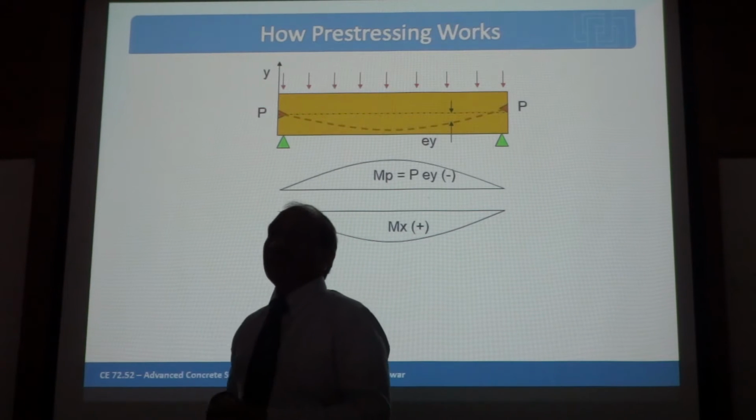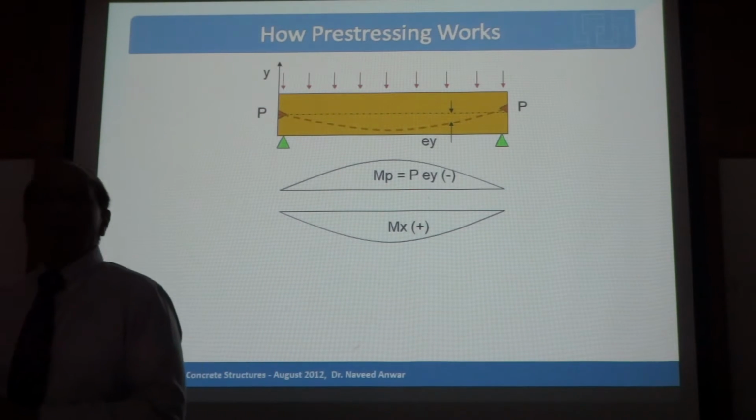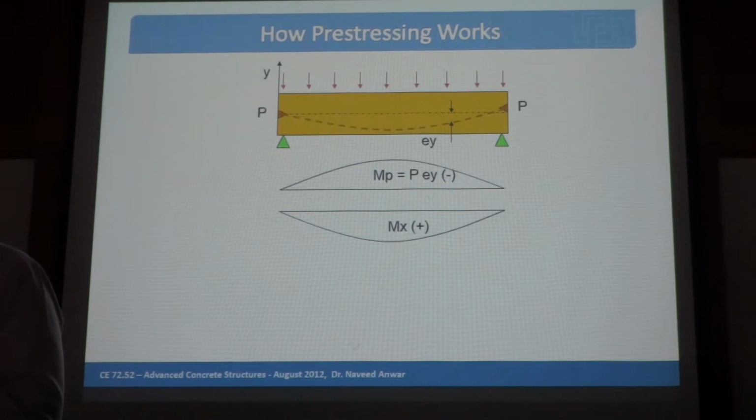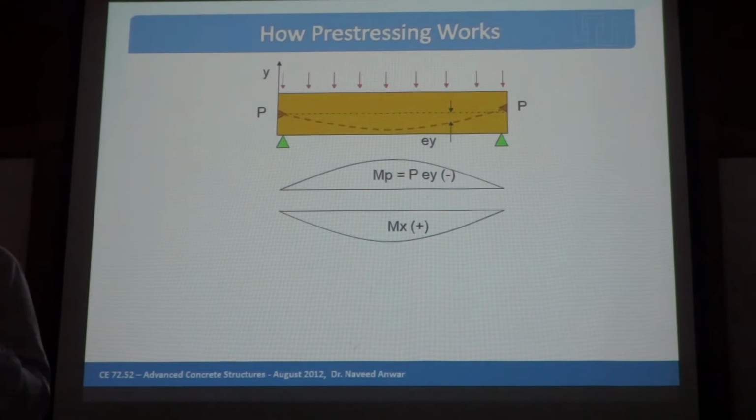This beam may have one point load, two point loads, some UDL. Some are live load, some are dead load. How do you balance them with a single tendon profile? Because you have to put the tendon there beforehand, but the loads are different, creating different bending moments at different load combinations.